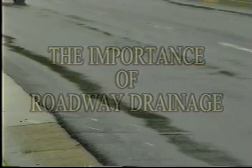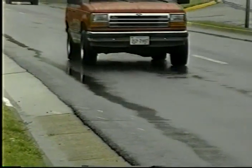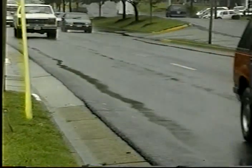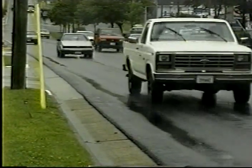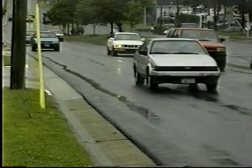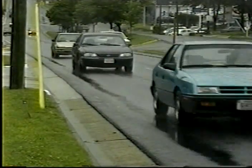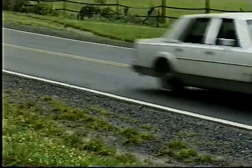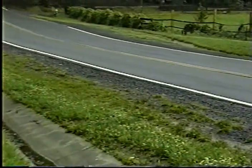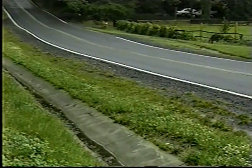Water is the most significant cause of damage to the roadway pavement and its underlying support section. Properly constructed road surfaces are relatively impervious. The hard surface protects the base support material from water and prevents surface softening and erosion. A properly constructed surface has a crown with transverse slopes on each side to drain water to the edge of the pavement and the shoulder.